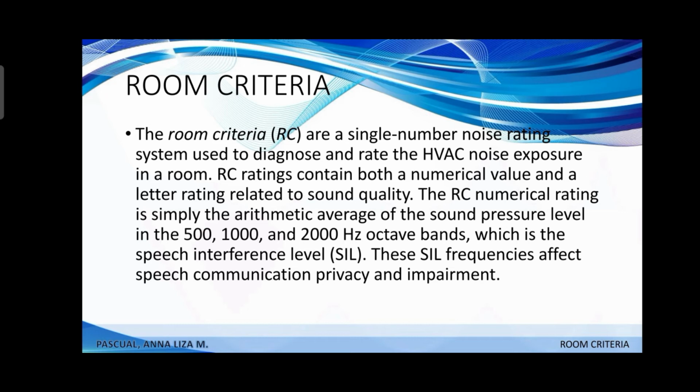An RC25N to RC30N is desirable in classrooms and lecture halls. A much higher RC50 value is acceptable in kitchens, shops, gymnasiums, and warehouses where noise is less of a concern. This RC rating is more effective than the NC system. It does a better job in rating noise with strong low-frequency content.